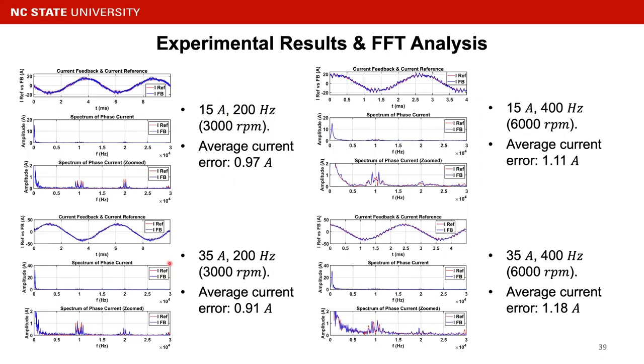So in this application, we target to emulate the very high frequency switching ripple current. Therefore, on the current sensor part, we selected a very high bandwidth current sensor of up to 1 megahertz bandwidth.